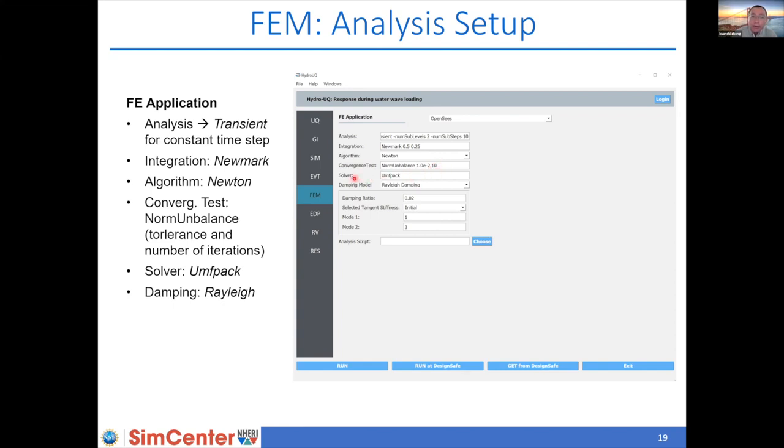And the solver, the fifth box, defines the system's equations, how they will be stored in memory and solved. The default one is the unsymmetric sparse solver, UMFPACK. Other available solvers would be the full general, so basically full band and symmetric band.